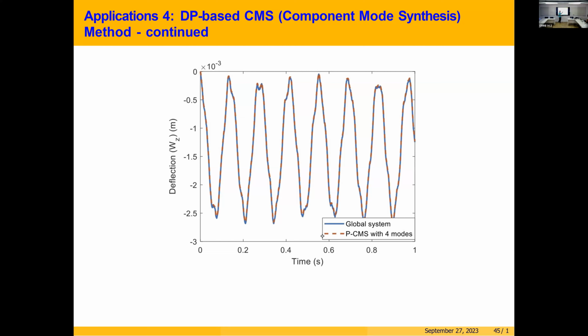And our error criterion, the mode selection criterion, is validated. It's linear algebra: the trace of an operator or matrix is the sum of its eigenvalues. And if that is stiffness, then for the inverse of stiffness, the trace is the sum of 1 over omega squared.